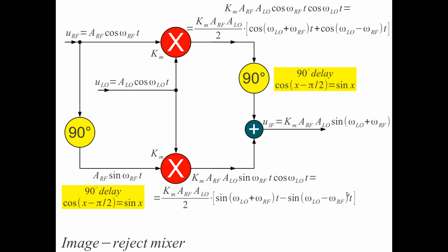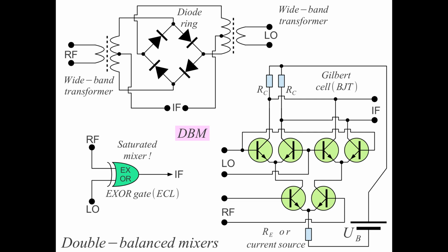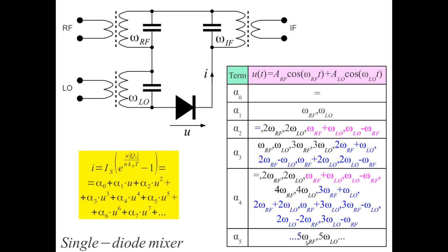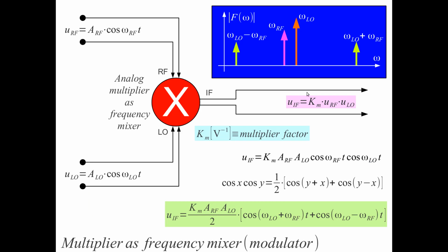In the best solution is around 40 dB. So also image reject mixers can be built, and we will see later on the application of image reject mixers. While for our discussion with single mixers, with block diagrams with single mixer, we are thinking about the double balanced mixer, because the double balanced mixer can suppress almost all of the unwanted responses of the circuit, keeping just the desired multiplication of the two signals, the desired multiplication we want here in our circuit. So this is what the mixer is actually doing, and this is the kind of component we desire to have in our circuits.